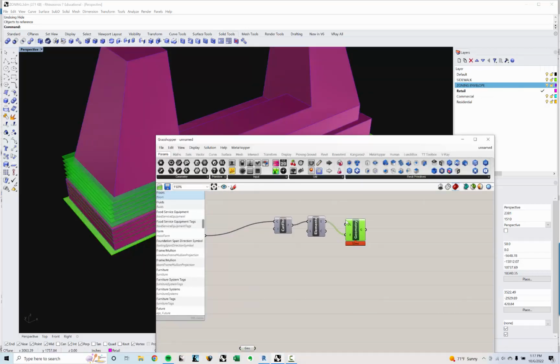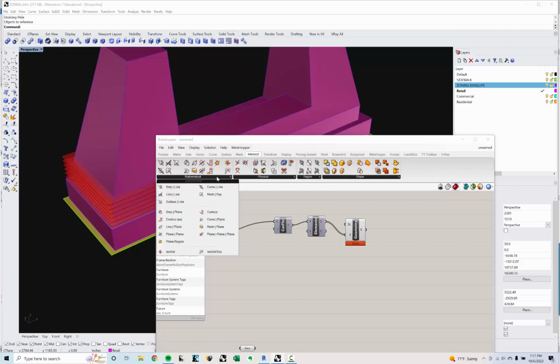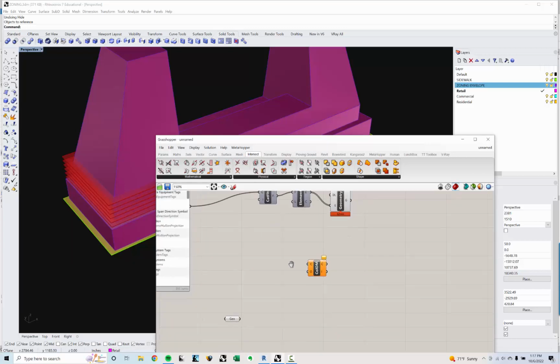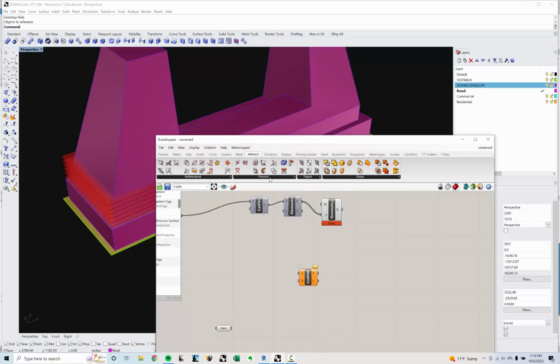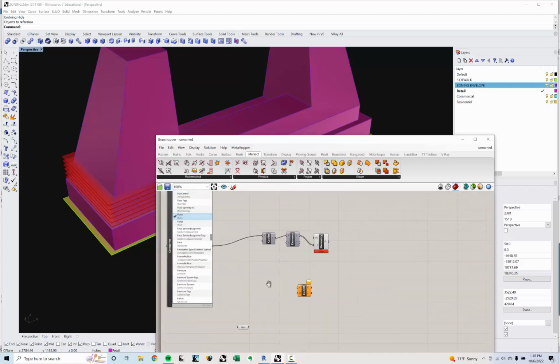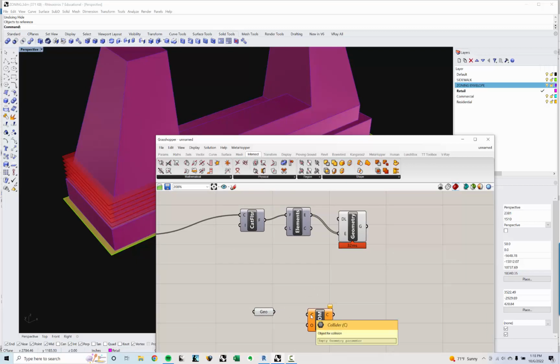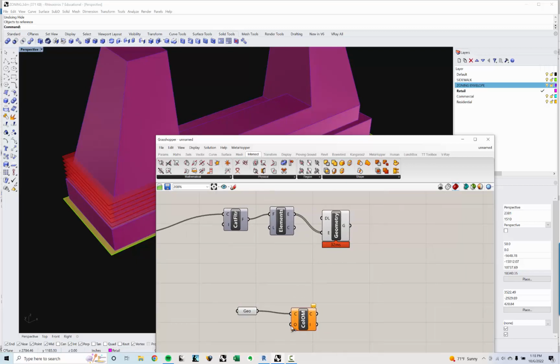Okay. And this is actually a simple component, which is just a basic Grasshopper component called intersect. And then I like to use the mathematical surface BREP, or it might actually be in physical. Oh, it's actually, I'm sorry. It's this collision one many component. This is a really quick, it's a much faster way. It checks to see if the elements collide, but it doesn't really indicate where. So all it's doing is checking collision or not, whereas the physical ones will actually give you the intersection curve or the overlapping geometry. We don't want that. We just want to check, does it intersect? Yes, no. And that's all we need. So the object for collision is our zoning envelope, and then the obstacles as a list are those.